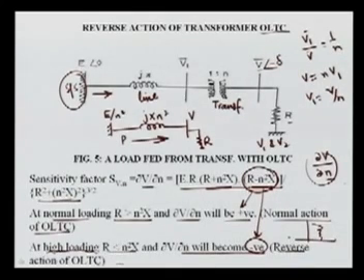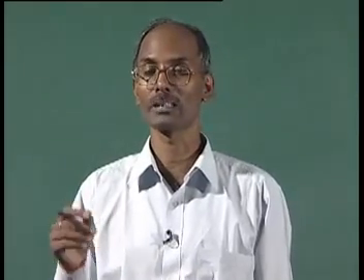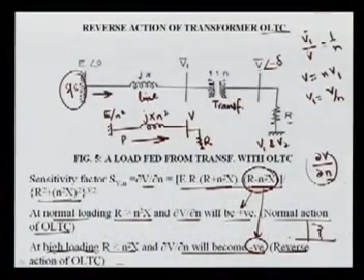So the reverse action shows that when you want to increase the tapping, for example increasing the tap to increase the voltage, the action is reverse, meaning your voltage is decreasing. Further, your transformer will try again and again, and finally the voltage will collapse. So this is also a very adverse phenomenon in the voltage stability case, and it only happens at the higher loading.